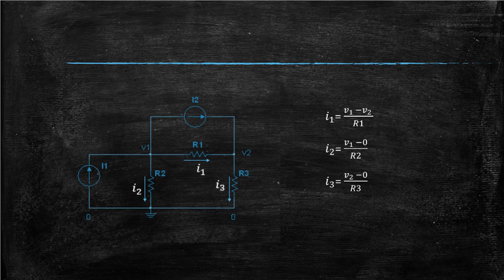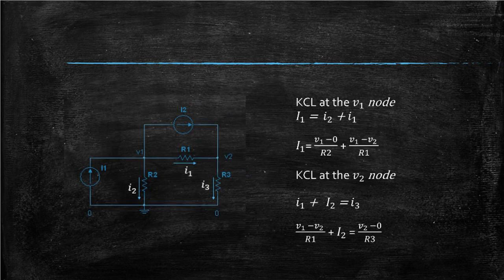All currents entering and leaving each non-reference node have been labeled. Expand the current equation of the resistors using the formula from before so it can be used in the KCL equation. Using KCL and the currents from all elements, find the equations. Finally, connecting and solving the equations is what you will do if we had values. So let's move on to an actual example.